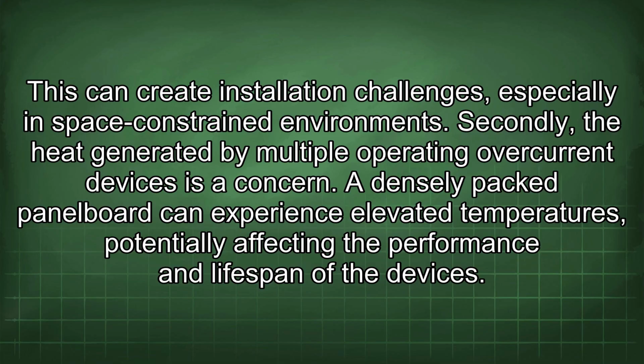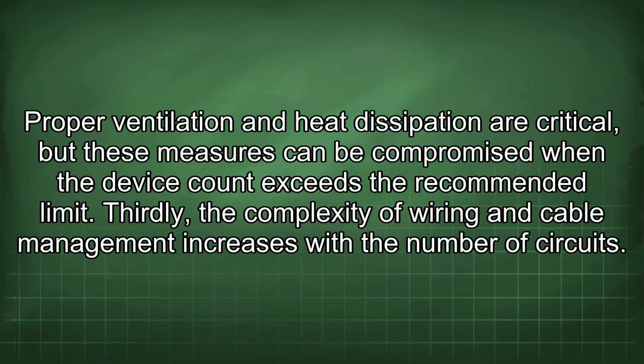Secondly, the heat generated by multiple operating overcurrent devices is a concern. A densely packed panel board can experience elevated temperatures, potentially affecting the performance and lifespan of the devices. Proper ventilation and heat dissipation are critical, but these measures can be compromised when the device count exceeds the recommended limit.